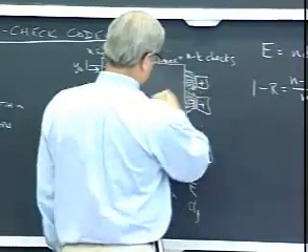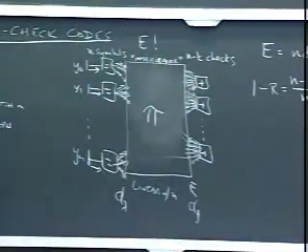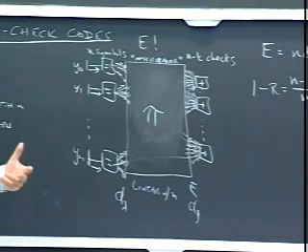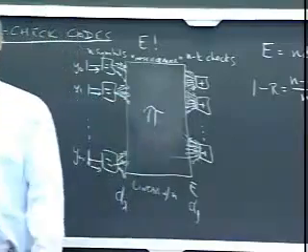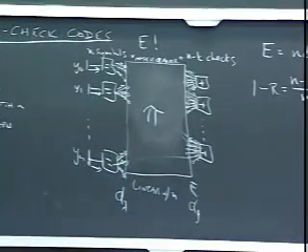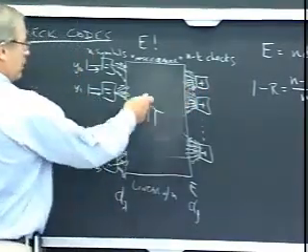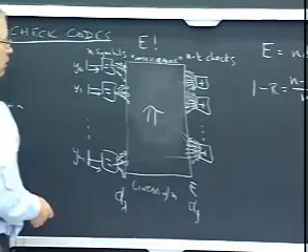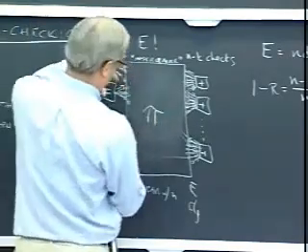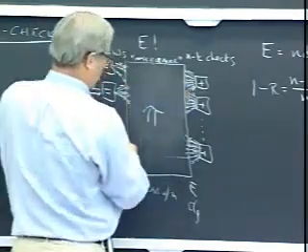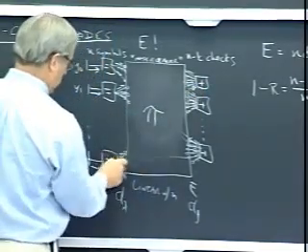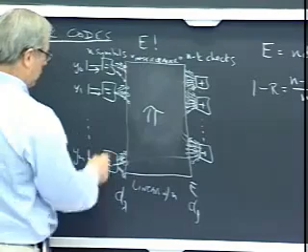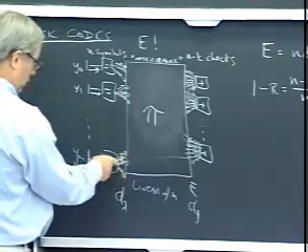We add them all up, and that gives us now a recomputed likelihood, a message consisting of probability of 0 given what we've seen so far and probability of 1 given what we've seen so far, that now goes out. Hopefully that's got some improved information in it now coming from all different parts of the graph, extrinsic. So this eventually will come back somewhere, say here, and similarly on all the other lines.